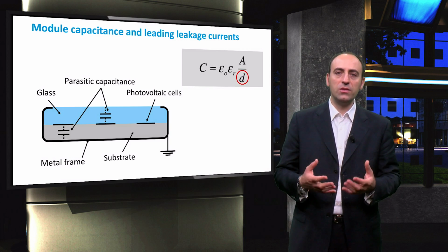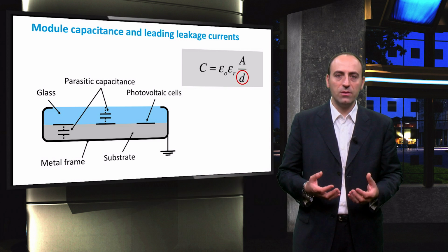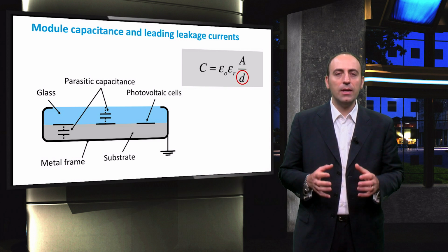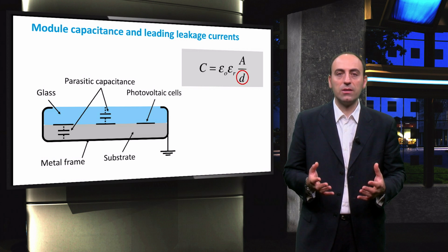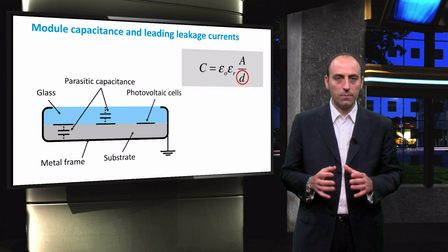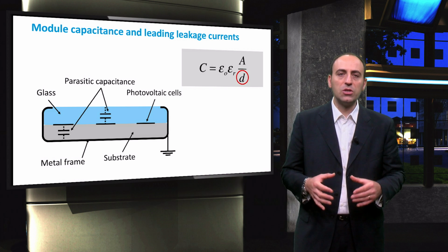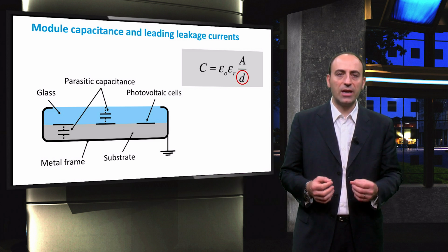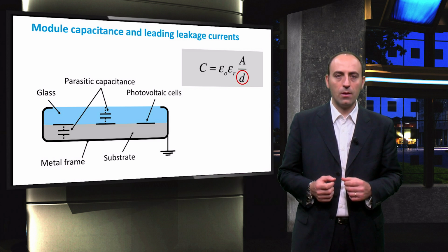Leakage current or discharge current is a reactive current with its phase shifted by 90 degrees to the grid voltage. This means that this current is lossless and not dangerous on its own. However, this current can superimpose a possible residual current and obstruct its detection by safety devices.